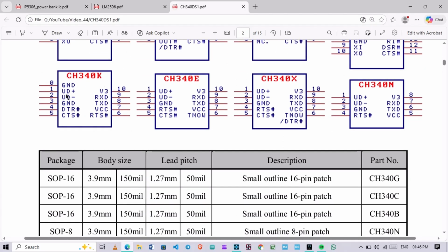So guys, here you can also see this is the ground 0 pin. That means this is the pad on the bottom side, there to dissipate the heat. So here I will add this pin also, just for your reference, but there is no need to add this one in the schematic view, from the perspective of the schematic. But if you are designing the layout of the final product, this is like a footprint, and definitely you have to provide this pin there.